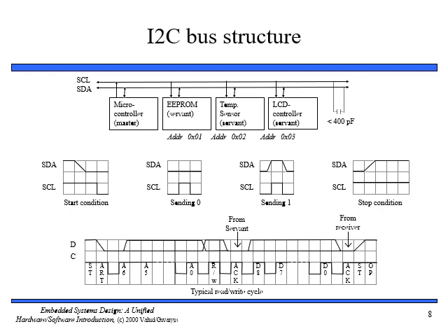One of these devices, the microcontroller, is the master. The other three devices, a temperature sensor, EEPROM, and an LCD controller, are servants. Each of these servants is assigned a unique address, as you can see in the figure. Address for EEPROM is 0x01, address for